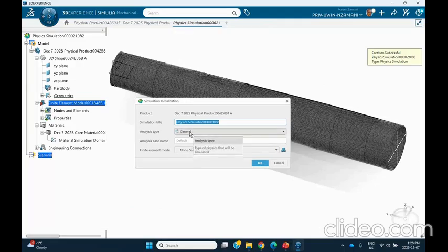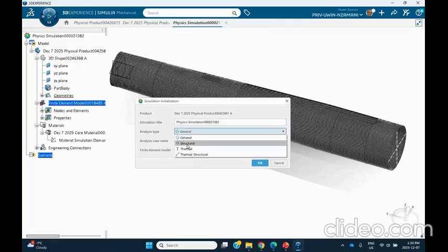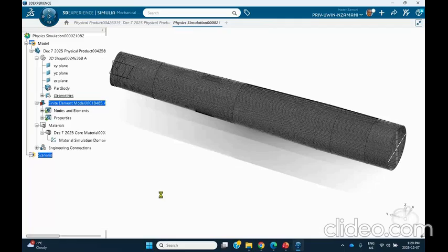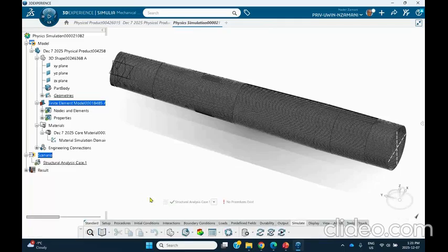All right, so we're going to do structural analysis, and we already created a mesh here, the finite element model. We already created that by meshing, by applying section properties, etc. Good. Okay. So first thing we're going to do is a static analysis. So we go to procedure, static.